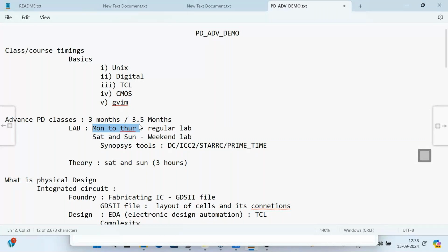Analog design engineer is not part of the ASIC design flow. They work from scratch. Every design we cannot implement using Verilog code. I cannot write Verilog code for amplifiers because those are analog circuits. If I want to implement an amplifier, a differential amplifier, or an op-amp, I cannot implement it using this flow, because this flow starts with what?